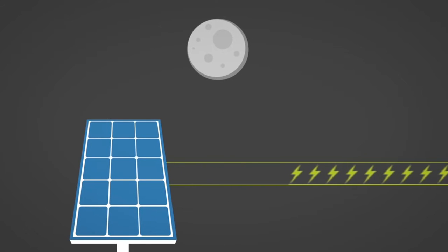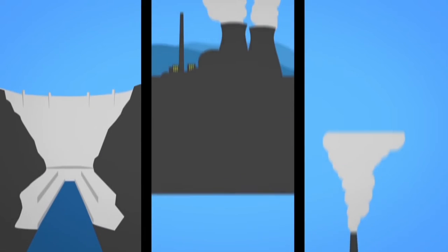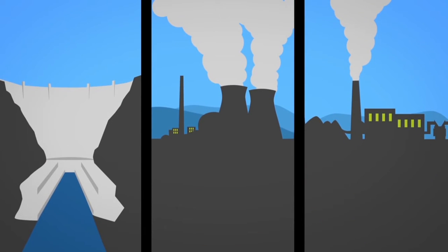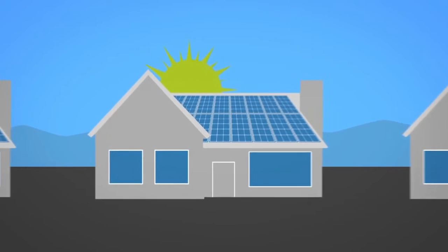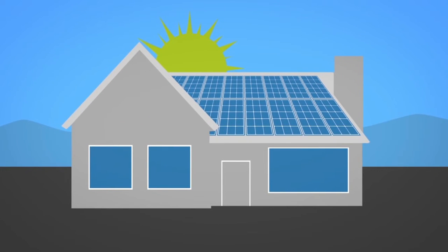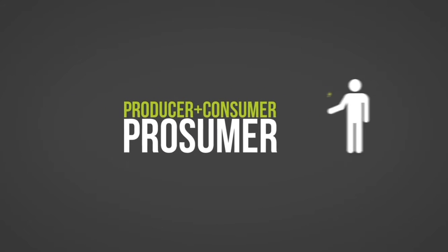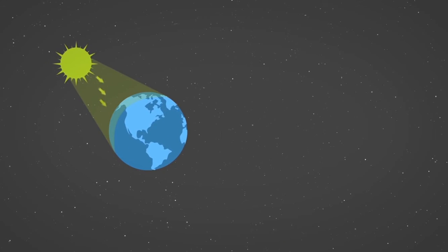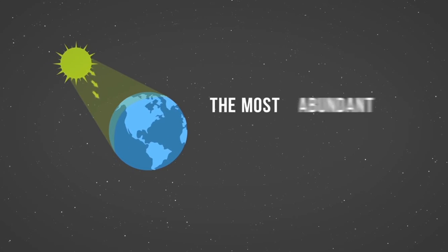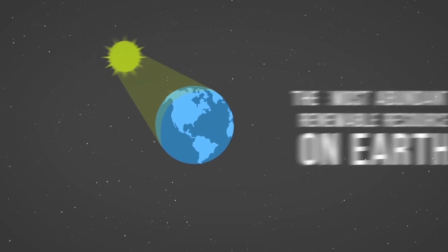Land use. Large utility-scale solar panels take up a lot of space, which can result in environmental degradation and habitat loss. Solar farms that cover a large amount of land are likely to have an impact on the local fauna and flora, particularly on birds. Solar farms can also inhibit local vegetation growth and damage agriculture. Unlike wind energy, solar panels aren't able to share the land they occupy for other uses.